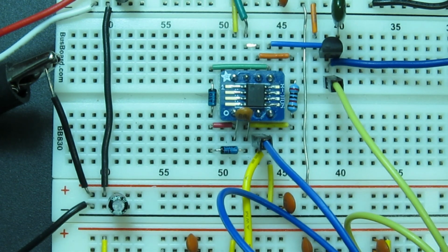I started with Schottky diodes because I wanted to see how fast I could push this circuit using a relatively cheap CMOS op-amp. But I know they're notoriously leaky, often a few nanoamps at room temperature, or up to a few microamps if you run them hot. They're surely not a good choice for this circuit at very long hold times.